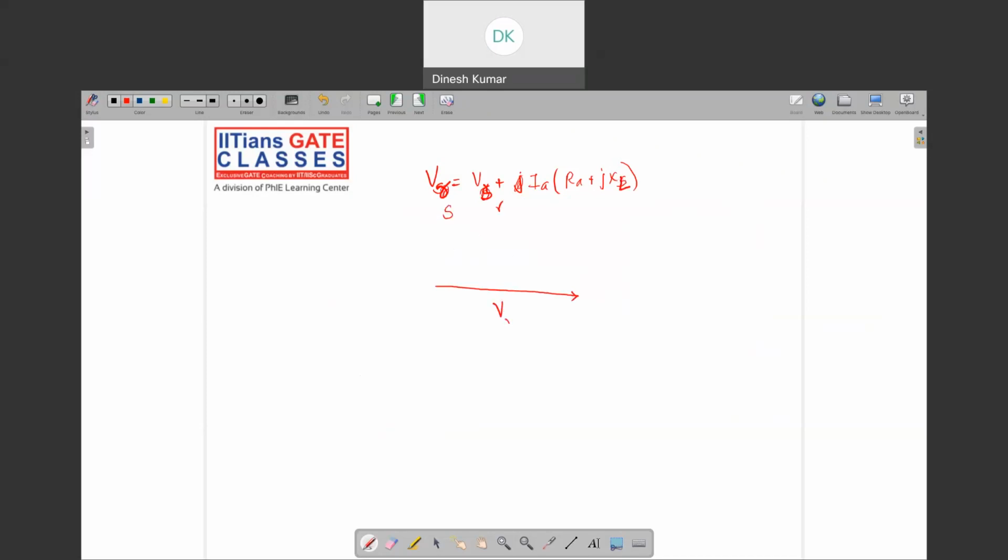Okay. So we can take the V receiving end voltage here and assume that this current is lagging with some power factor angle phi. This depends on the load. If an inductive load is connected on the transmission line, then the phi will be negative, lagging the voltage. If some very high leading load is connected on the transmission line, then the current will be leading, like that.